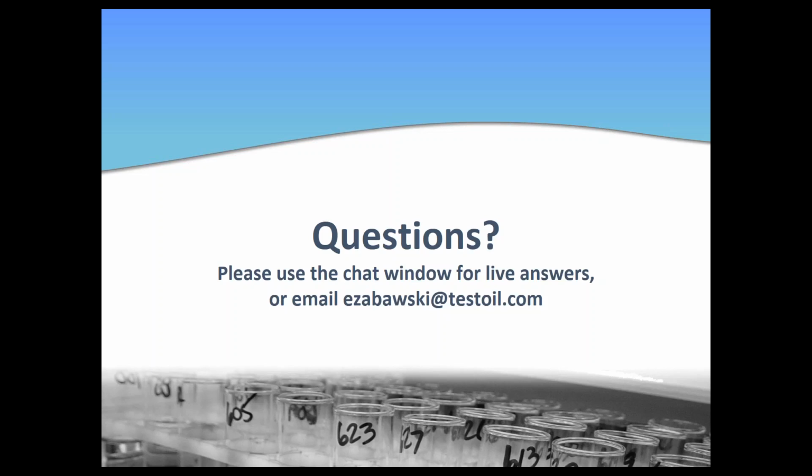Transmission fluids, there's nothing really terribly unique about a transmission fluid. It shouldn't cause you any different issues than a standard hydraulic or engine oil when it comes to measuring in a Karl Fischer titrator. People tend to only have issues when it comes to the really thick oils, like gear oils.